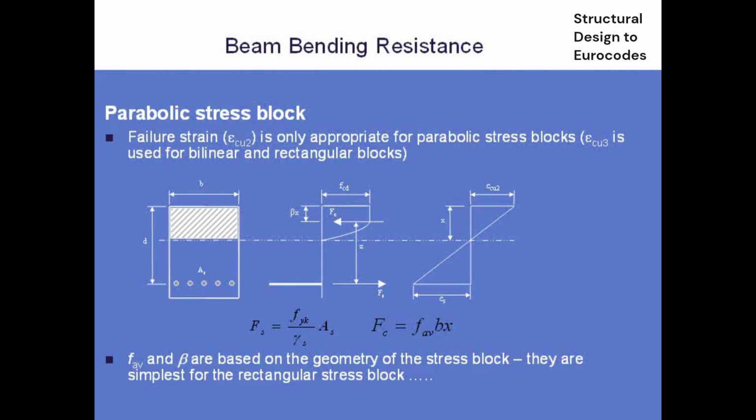Right. Just for the purpose of the notes, again, I think we should use computers, and Sam will do these analyses for us. But what you have on the slides and also in the book are some simpler ways of calculating things by hand. A useful parameter in the notes is the force Fc, made up of a function of the neutral axis depth x and the average stress fab in the compression area.